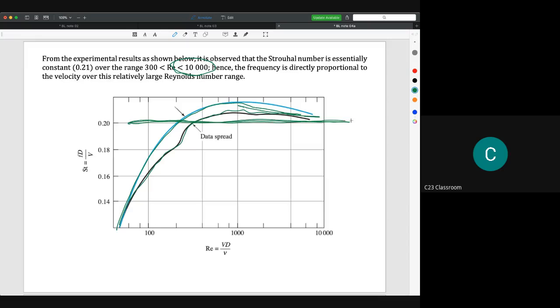If you read back the question about the Strouhal number in our chapter 1, we find that the value is actually 0.2. This is the reason why normally people start with 0.2 for any situation that may have possibility to swing. Later on, I will show the phenomenon.